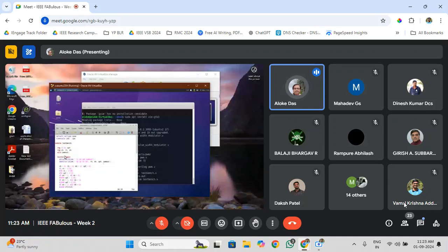See, module testbench, and the test bench doesn't have any input or output ports. And you have to instantiate the DUT, design under test, which I have instantiated here. This is my module name, this is the instance name, and the port list of PWM, and the connections of these signals to the test bench signals. I have defined all these signals here, and I am displaying this.